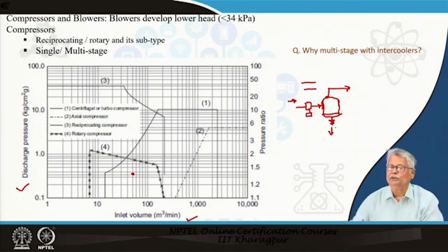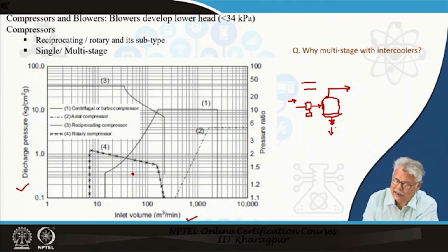This is something very important for you to know, that often the moisture which is getting compressed along with the air will be condensing inside, and you have to periodically drain such compressors which are taking suction from the ambient air. That means if the air is wet, the condensation will be there in this particular vessel, and you have to drain it periodically.